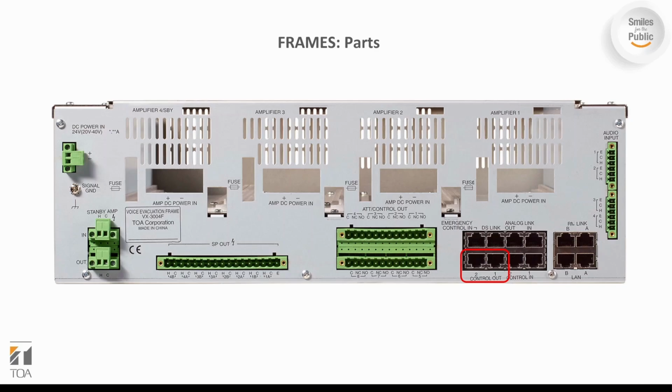The control output ports allow for connection of 4 pairs of dry contact outputs per RJ45 port. This allows for the VX3000 to trigger third-party systems depending on programmed trigger events. Similarly, there are also relay control out outputs which are similar in function to the dry contact outputs. These can also be used as attenuator trigger connections.